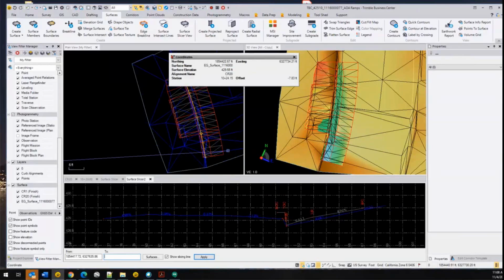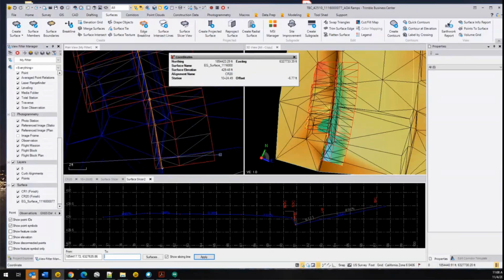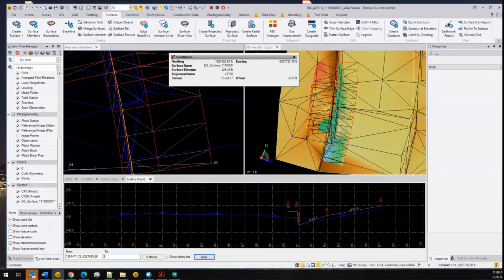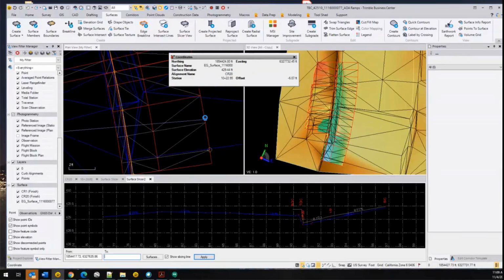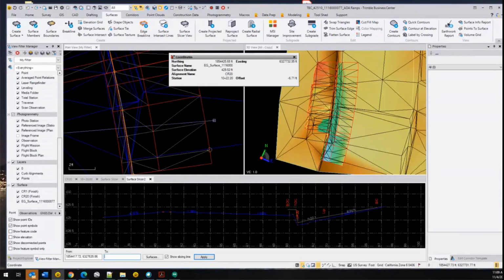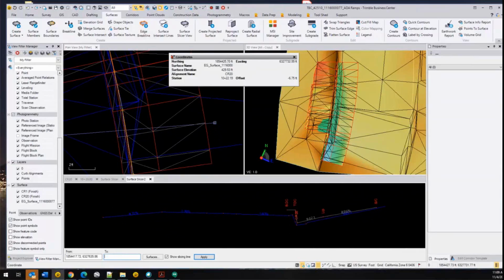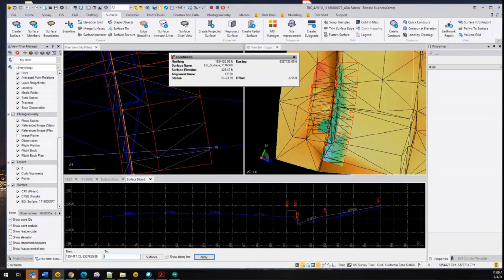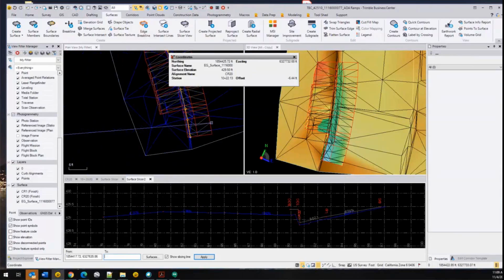We're getting a little bit squirrely right here. One thing to keep in mind is since we're entering elevations, it's going to prorate those elevations between here. So if our EG surface, like in between these templates, is off a little bit, I'm not going to get too concerned about that. And in this case, we're looking at it being well under 1/10. So I'm not concerned at all here. So that's checking our saw cut.